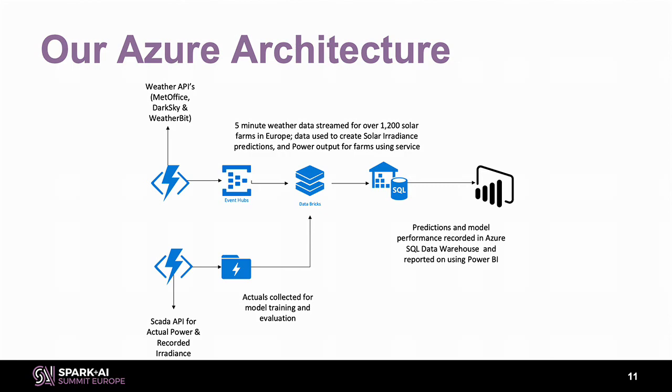So we take as many weather providers as we can get, capture all of the data, and generally we average this out across different predictions. We run our model across each of the different weather forecasts, slightly tailored depending on what features are present in each forecast, and then we'll average that to give us irradiance and power. The team are also looking at investigating into the seasonal trends between the different providers.